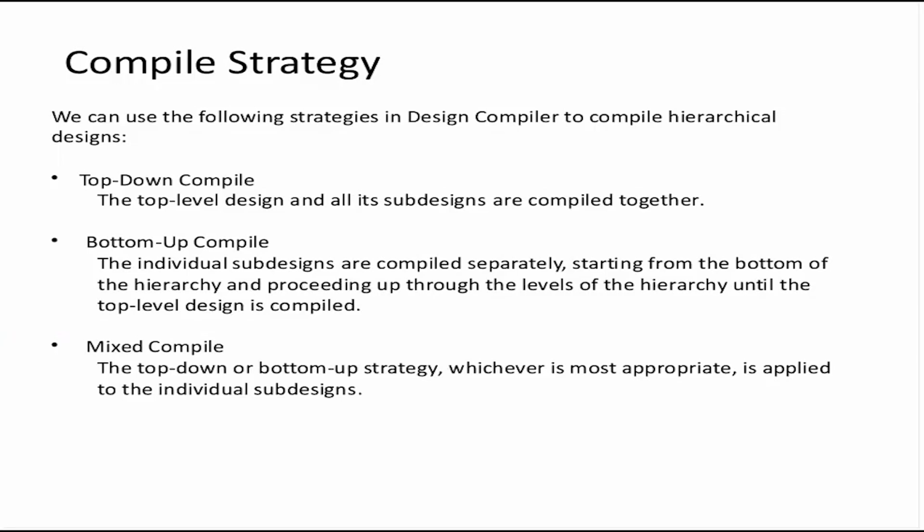Top-down compile, as the name suggests, starts from a top-level design. All the parts of the design, all the different RTL files, are read in, and there's only one compile stage. Here DC will attempt to synthesize the complete design in one go.